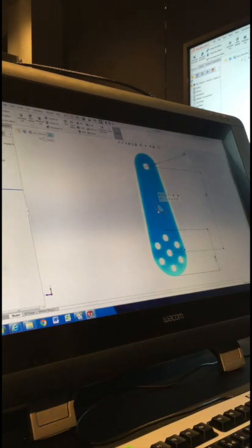Having that Instant 3D unchecked, when I click on that, you see how those dimensions don't come up. All right. So the Instant 3D, which by default should be on, typically just leave it on, that lets you very quickly click on your part, your design, and then click on the dimension, and you can type in a new number. So 70, press enter, and it'll update the shape. So you don't need to go and edit the sketch. You can just click on it, put the number in, press enter, it'll update.